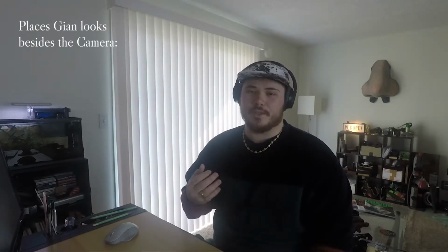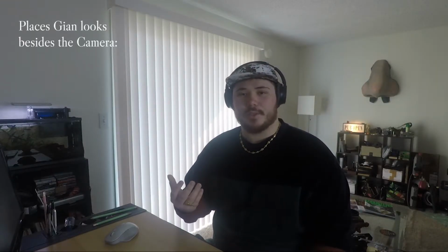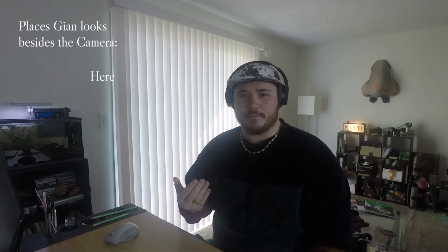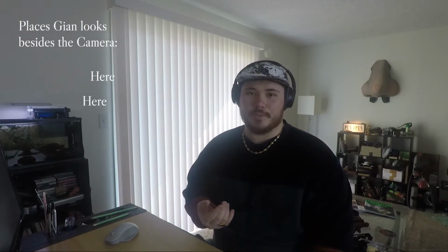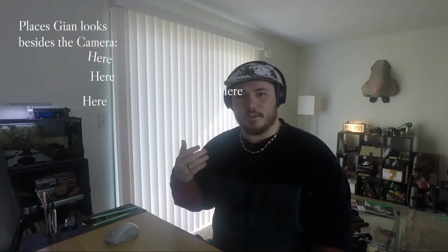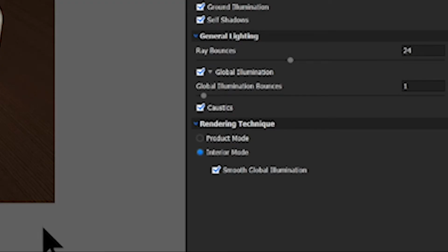This setting is the key to realistically rendering glass and liquid, but if you're not working on a super powerful machine, it can really put the wringer on your computer, as can a whole lot of ray bounces. Both of these things can lead to fireflies or other hiccups in the renderings that you might produce. At the bottom here, we have rendering techniques. Product mode is optimized for products, and interior mode is optimized for interiors, specifically in relation to whether the camera is in an enclosed space or not.